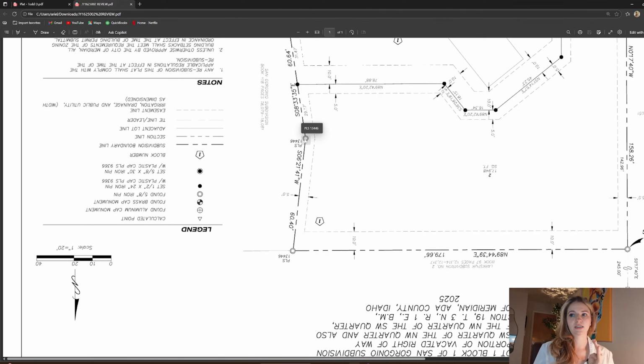And then once you get to 60.4 feet, you're standing on this point now, and again it's saying start facing due south, and you're going to go only 8 degrees, 33 minutes, 35 seconds, but this time it says east instead of the previous one said west, so we were turning towards the west, but now we're going to turn towards the east, which would be to our left. So we're just going to pivot, and then we're going to walk. This is 29.17 feet, and that's how you get to this point.